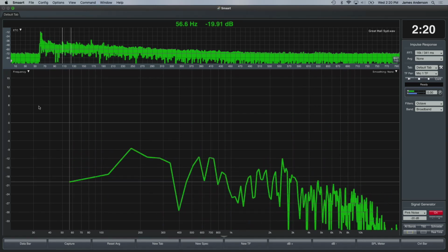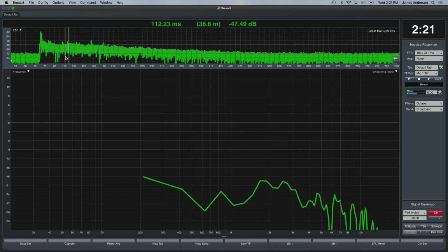All we're doing is choosing a chunk of the signal to look at, and we're running a DFT, so it's an arbitrary length. We're not using an FFT. FFTs are set lengths, powers of 2: 1K, 2K, 4K, 8K, those things. One of the things you'll notice is that as I get a narrower and narrower window, my frequency resolution goes down, because my frequency resolution is 1 over the time constant of the FFT.